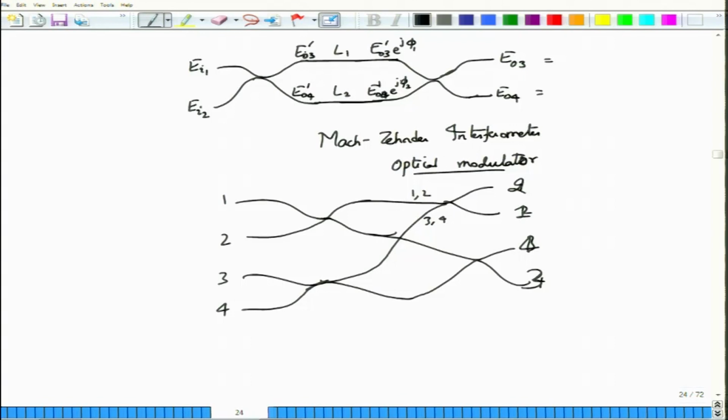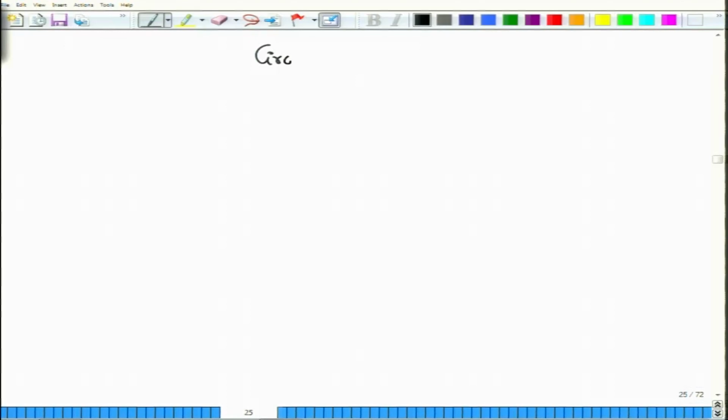Okay, let us move on to a circulator. We have already talked about a circulator, so I don't have much to add. I'll just review this one. A circulator is, most of the times, a 3-port device. You have port 1, port 2 and port 3, and when you launch a pulse in port 1, the signal that would go will be to port 2, but port 3 also will usually have some signal, and the difference in the power levels is essentially the isolation.